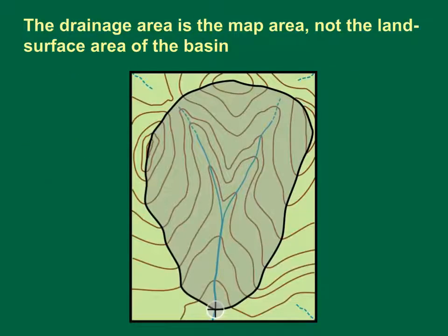The basin drainage area is defined as the river basin area projected onto a horizontal plane and enclosed by a topographic divide so that the direct surface runoff from precipitation normally would drain by gravity into the river basin. This image shows our hypothetical basin with the area in gray. The projected area is used because that, by and large, defines the local flux of precipitation into the basin. In some areas, the groundwater and surface water divide may not be the same, which will affect the amount of groundwater discharged to the stream.